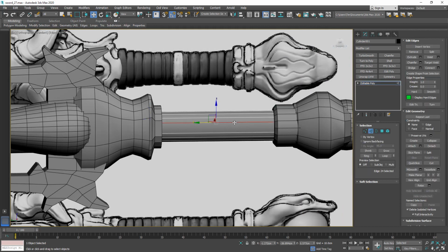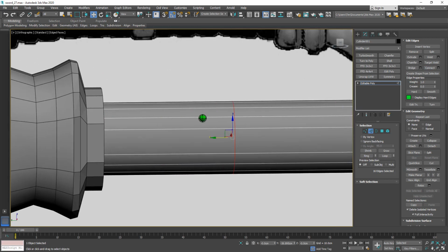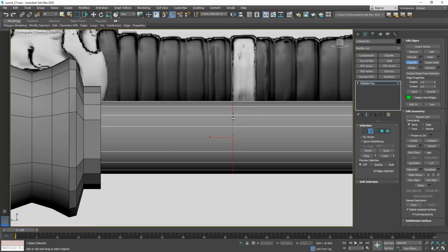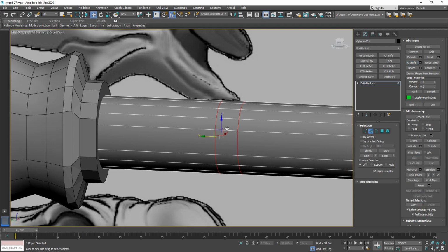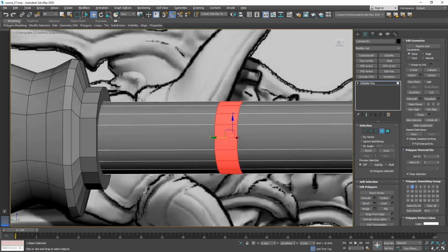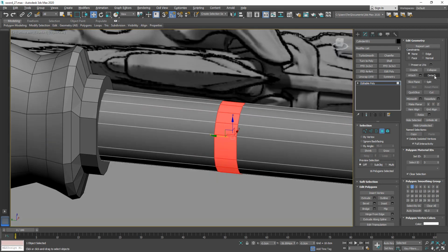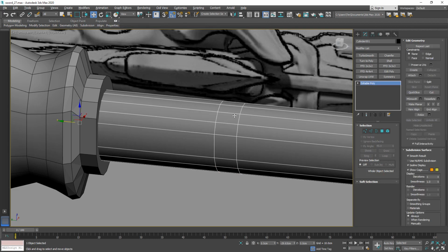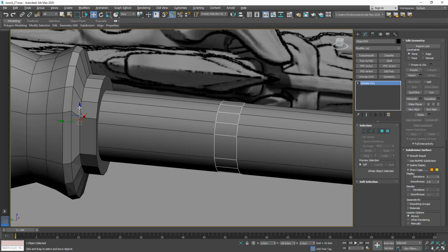Now let's go here and make a ring selection on that element, make a connection here. And I should have just made 2 edge loops, but we can get 2 if we just chamfer that. Basically that splits it apart here with that chamfer tool that we have there. And now I'm gonna make another polygon selection here out of that and detach it. Detach as a clone. And then sometimes it's a bit tricky to actually select then this clone, but you can see we have it now.